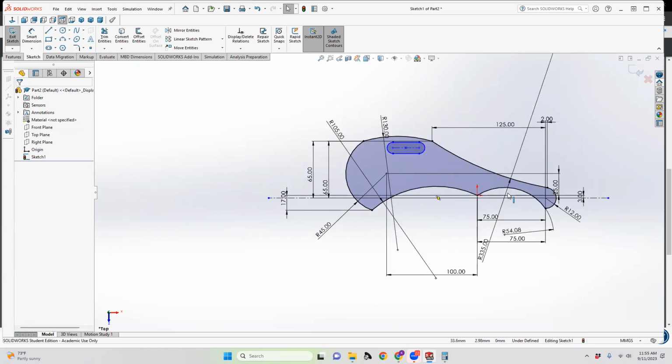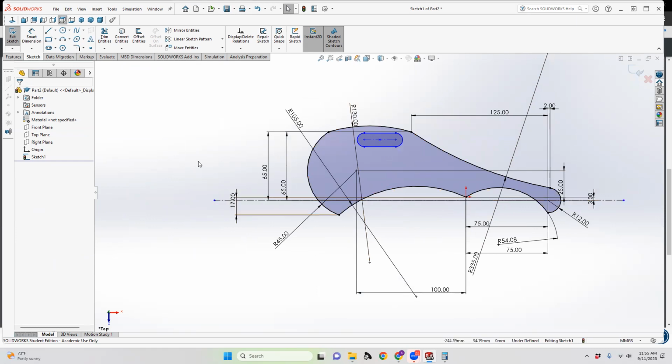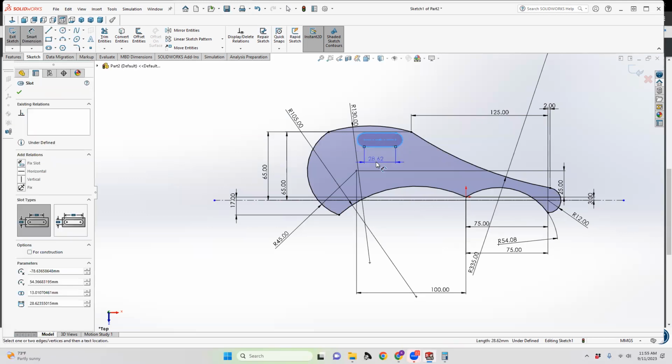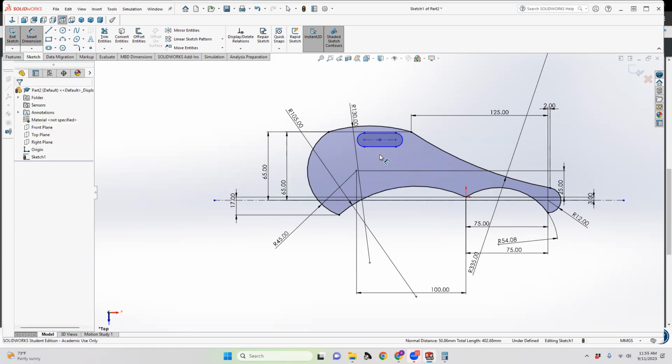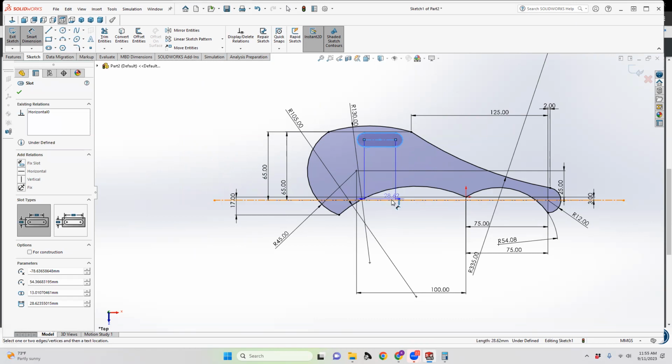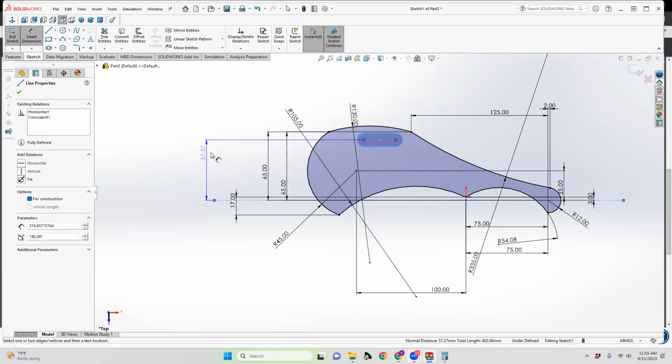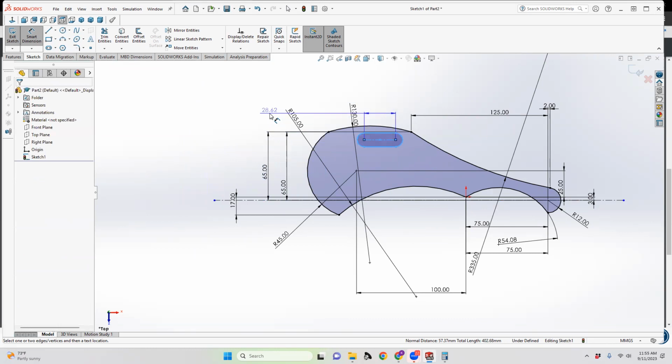The reason you want a center line is for this next part of the feature. If we look at it and say, I want to look at the angle between two things, instead of looking here at just the width dimension, if you also select somewhere in the middle of a center line, you can get an angle between those things. But in this case, because they're already defined as perpendicular, you're going to get a perpendicular distance. So there's a couple ways that you can get around that.